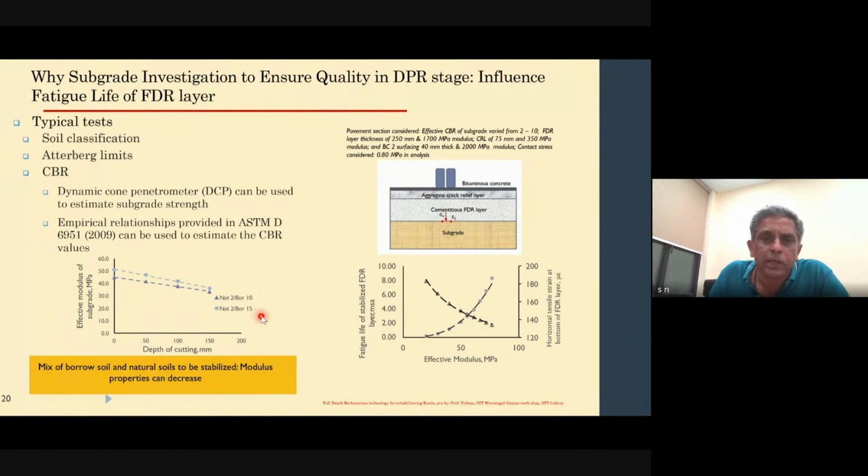Now, the next thing is how to estimate cement spread. Now you are actually doing a mix design where you will be given a weight percentage. Let's say for a given mix, you have to add 5% of cement in that mix. Now that is a volumetric or a weight-based estimation which cannot be done in the field. You are actually going to have to spread the cement laterally, horizontally, and it can only be estimated based on area. So volume has got to be translated to area when you are estimating the cement spread that is required.